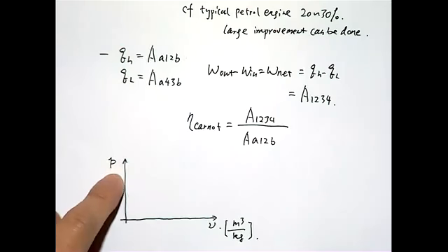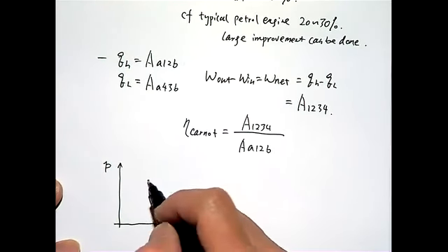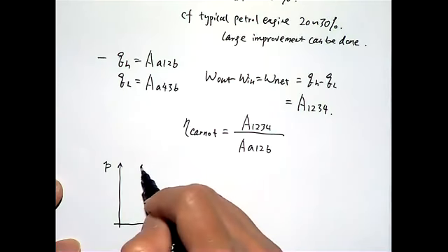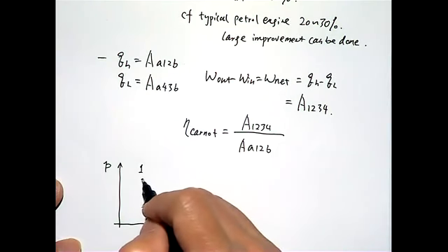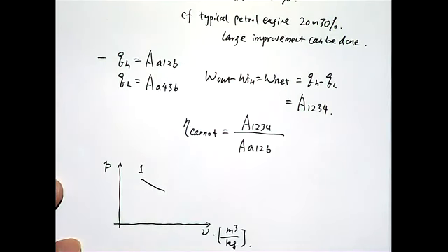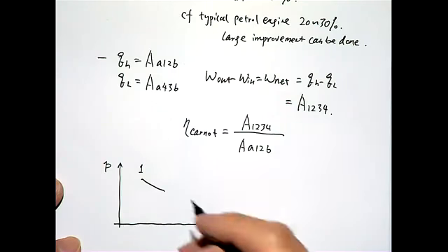So in this case, we can also draw the Carnot cycle, and draw any cycle if we want. Let's say we're starting from state 1. It's an isothermal heat addition. So in this process, we'll have a curve. It's not a straight line anymore because pressure and volume, none of them are constant in this case.